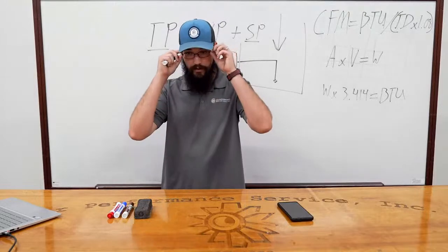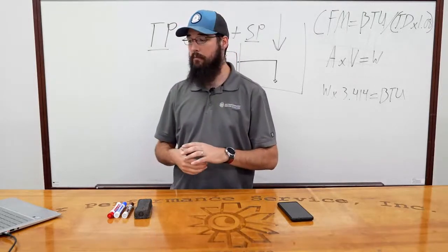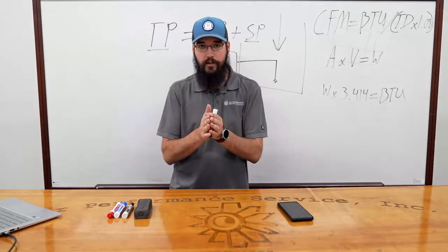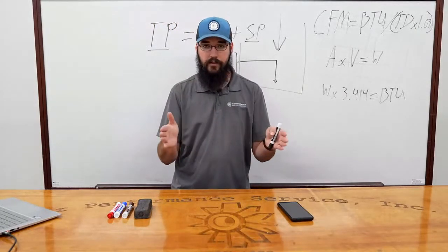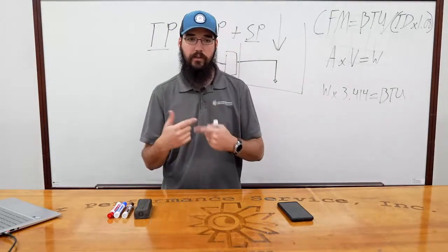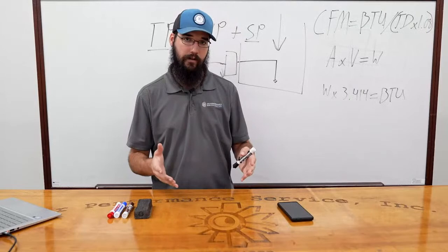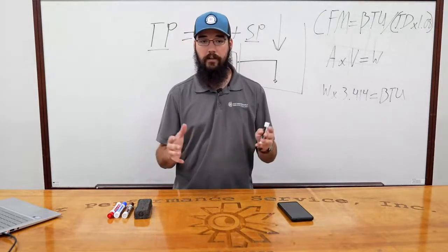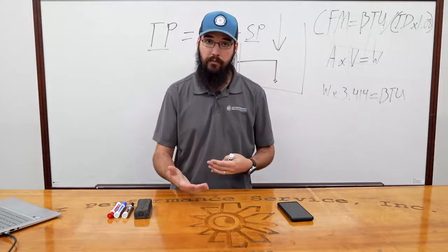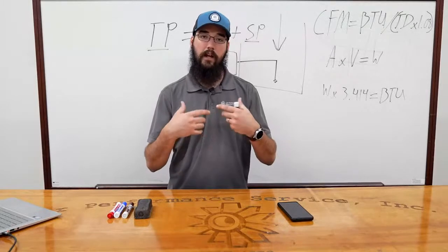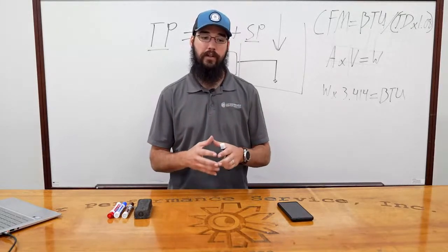So that's the two things that I see most common. They will either be all the way adjusted in, or they'll be all the way adjusted out. And typically, in most of those systems where I run the math on what's happening, I find that it's too far one way or the other. Somebody just didn't take the time to properly commission that pulley and that fan system, and they're not moving the correct airflow to get the most out of it.